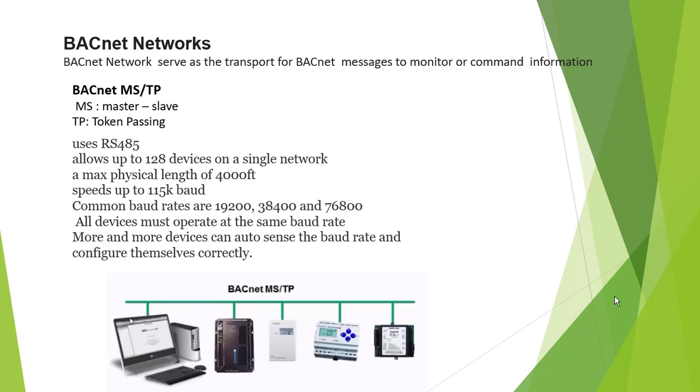This communication baud rate is most often 19,200, 38,400, or 76,800. All the devices must operate at the same baud rate on one network.